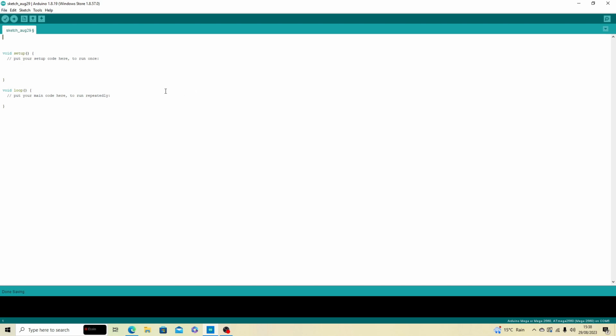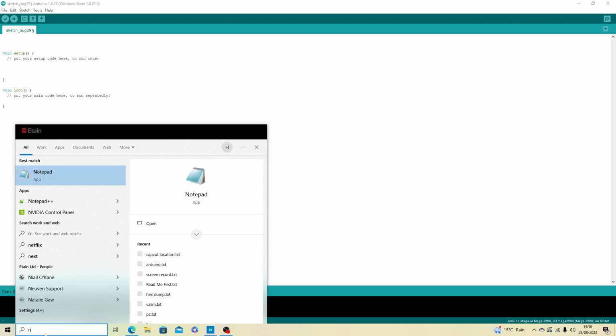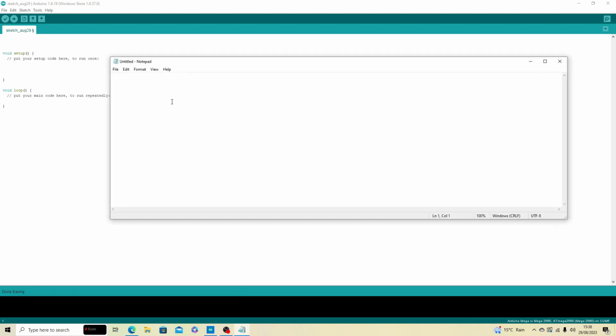All 20 address lines of the 8086 are connected to 20 pins on the Arduino Mega, and I want to display each address line and then that in hex. So what I would expect to see is something like this. If I just open Notepad, I would expect to see on the screen the address lines coming out as this. But I'd like to actually then total that in hex. So I'd get not only the 20 address pins and what value they were, but then the hex value as well. So that's what I expect to see coming out onto the screen.